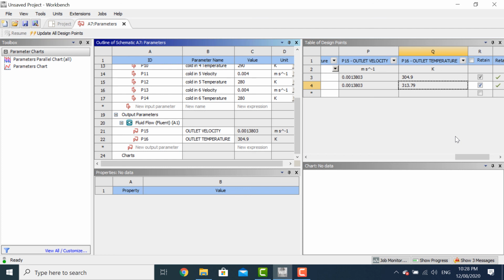In this tutorial, we get to know how to create the geometry in Design Modeler using extrude and revolve tools, generating the mesh with tetrahedron patch conforming method, and define the materials with cell zone conditions in ANSYS Fluent. Then we set up the simulation problem using energy equation and laminar viscous model. Also, we get to know about the post processing in CFD-Post and also how to perform the parametric analysis.